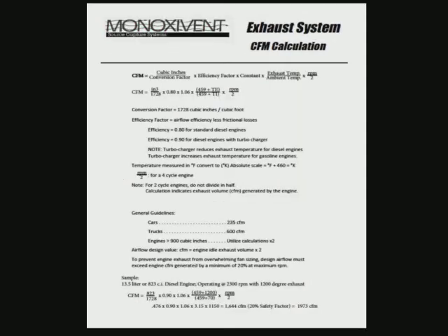Next is a CFM calculation sheet that we offer, and basically this allows you to fill in the needed information to calculate your CFM requirements. And again, note that this is not based on horsepower. Often we're given horsepowers of vehicles and asked to design a system. That's not enough information. We need to know, and we need to put into this equation the cubic inch, the exhaust temp, and the RPM. How is the engine going to be running?